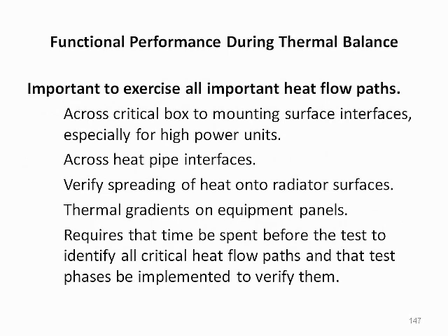During thermal balance testing, it is important to exercise all important heat flow paths. This includes heat flow across heat pipe interfaces and critical unit to mounting surface interfaces, especially for high-power units like traveling wave tubes, or TWTs. The spreading of heat onto radiator surfaces should be confirmed to be as expected, and temperature gradients on equipment panels should be measured.